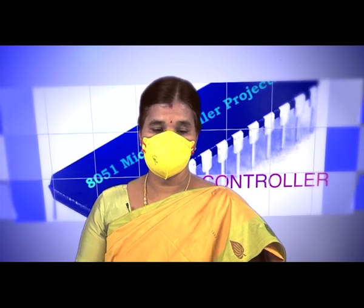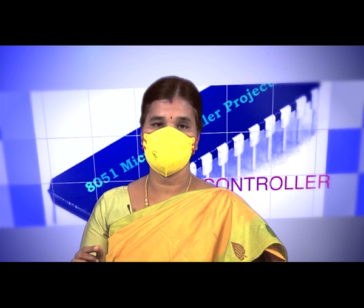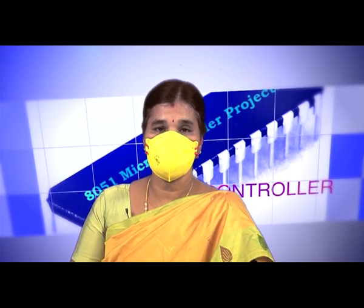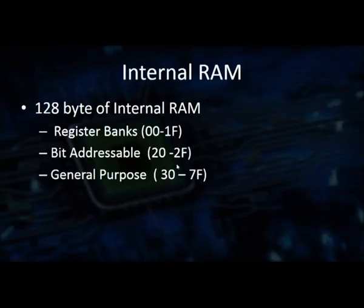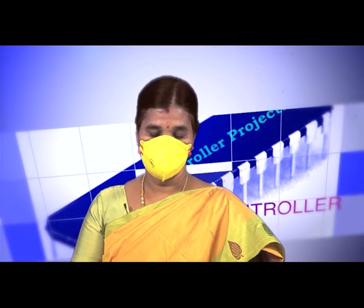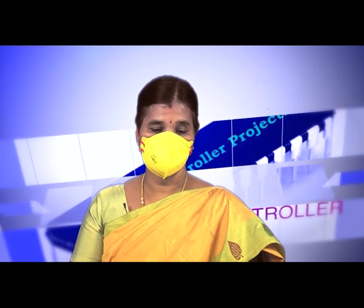But in a microcontroller, you can access the particular bit only. That is the advantage. The microcontroller can be bit and byte addressable. Then the remaining addresses 30 to 7F are used for general purpose, the user area, where the user can write or store any kind of their required applications or programs.